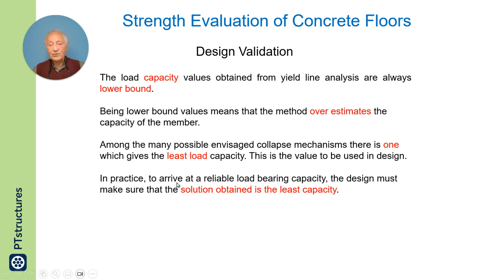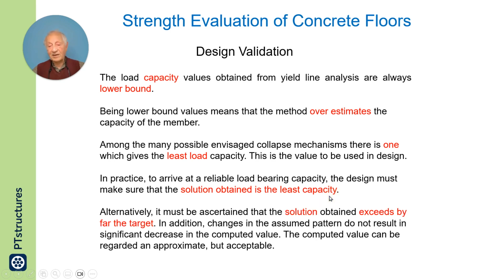In practice, to arrive at a reliable load-bearing capacity, the designer must make sure that the solution obtained is the least capacity. Alternatively, and that is what is mostly used here, it must be ascertained that the solution obtained exceeds the target by far. In addition, changes in the assumed pattern should not result in a significant decrease of the computed value.